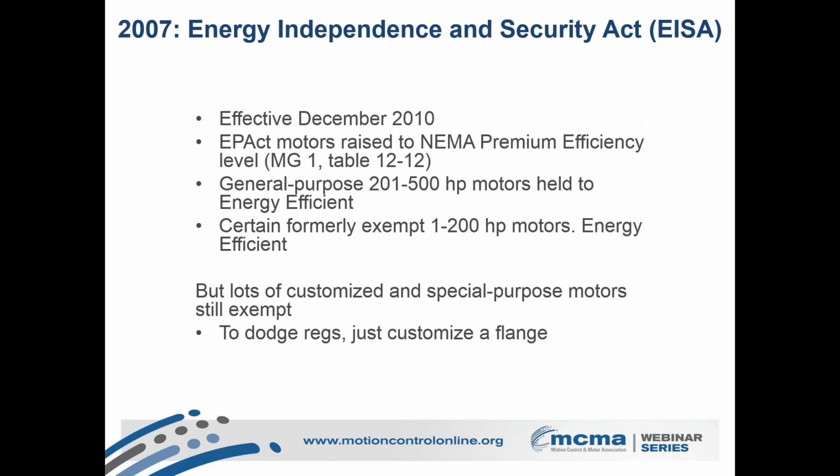It didn't do it completely, but it did raise the 1 to 200 horsepower motors from NEMA energy efficient to premium efficient. It also added 201 to 500 horsepower motors to energy efficient and pulled in some formerly exempt motors to energy efficient. So it did increase the stakes in all of this, but mostly you're looking at general purpose stuff, nothing modified, nothing application specific,